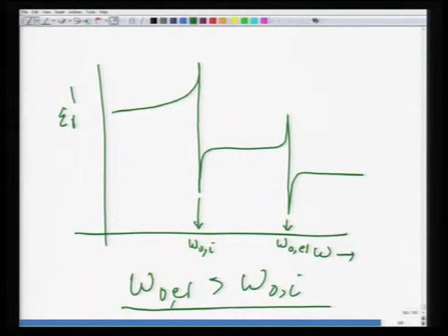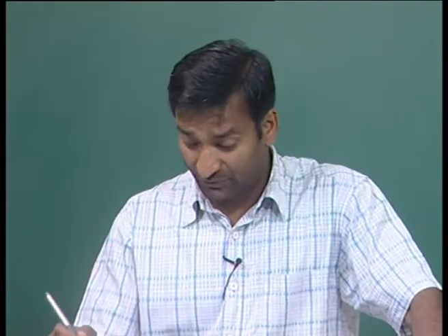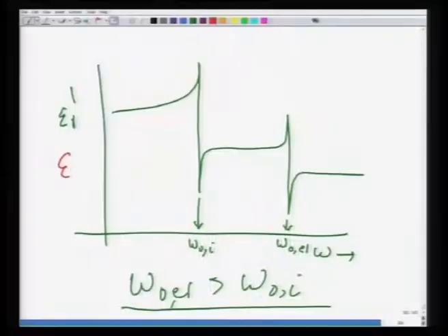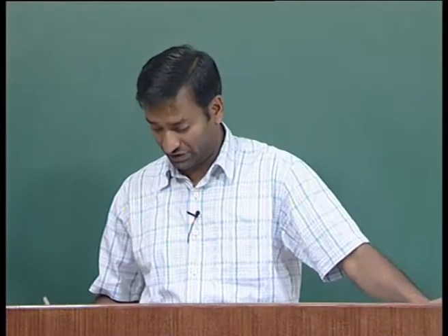Nevertheless, what they undergo is a phenomenon called resonance, and this characteristic frequency is the resonant frequency, where charges oscillate together with the applied field. So, they are in resonance with the applied field, and if you plot epsilon r double prime, this shows a loss at these frequencies. So, this undergoes a maximum in the loss characteristic. This is when they absorb maximum energy. As a result, the loss is maximum. So, this is typical of these two mechanisms, where you can consider a charged dipole as a linear oscillator.